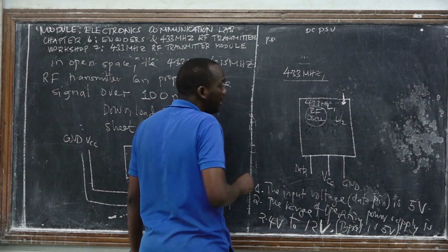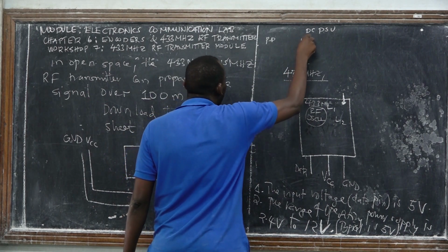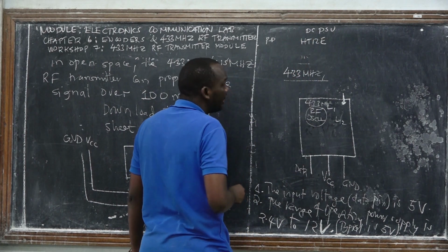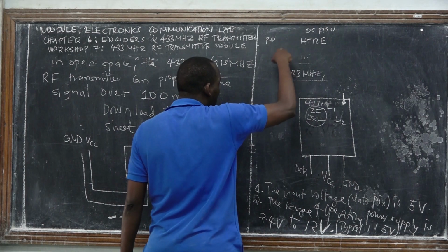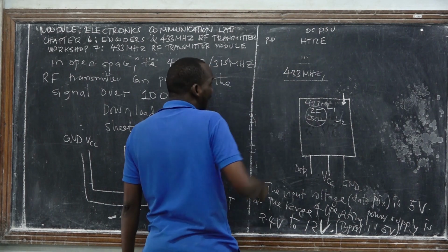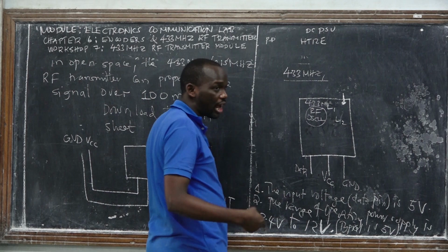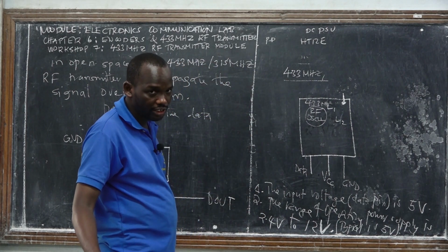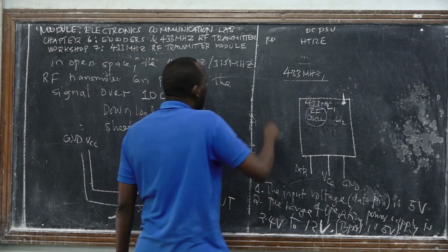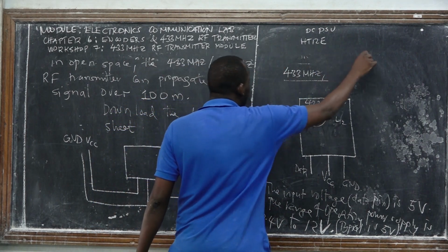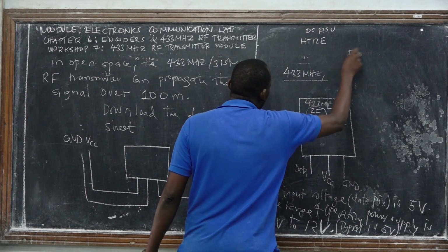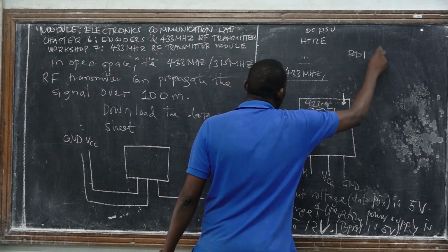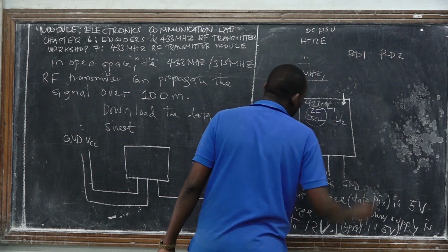And then here we had the HT12E encoder, whereby 5 address pins are connected to VCC and 3 address pins connected to ground, and also the pin 9 is connected to the ground. Then we have pull up resistor network number 1 and pull down resistor network number 2.